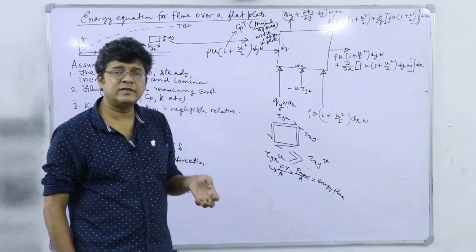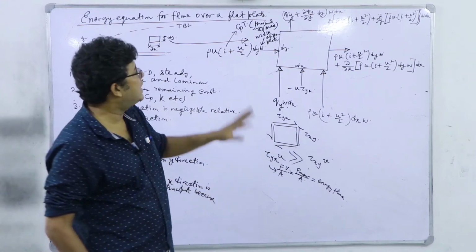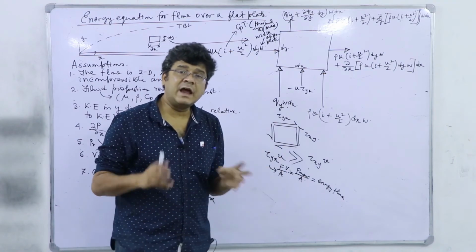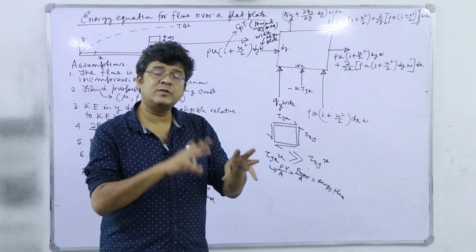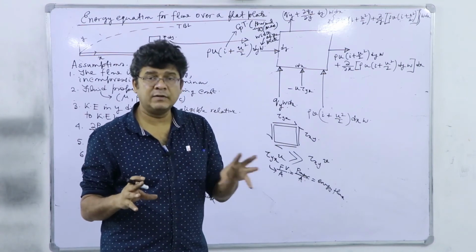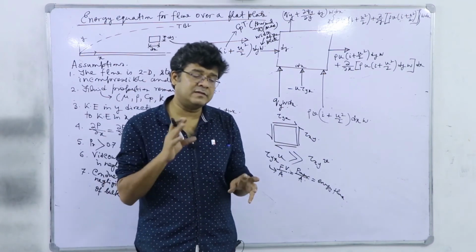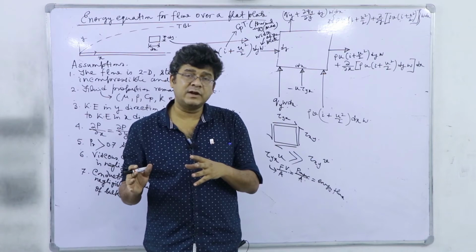So this transforms the energy flux with the appropriate sign, because truly we have to use this steady flow energy equation for an integral control volume. Here we are not going to do that. Here we simply write that all energy fluxes will be equal to 0, but that we cannot write. Why can we not write that? Because you see, for this control volume analysis, q dot minus w dot is equal to the steady flow energy equation that we have derived.